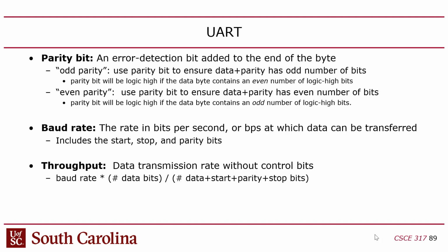So normally, if you get a new peripheral and you want to talk to it over JTAG, UART, you're supposed to look at the data sheet and find out how to set up your terminal properly to talk to it. Or you can just guess like Philip and I do. You might ask, what happens if you set it up wrong? Well, you either get nothing at all, or you'll get gibberish, garbage. So it's pretty easy to know if you got it wrong.